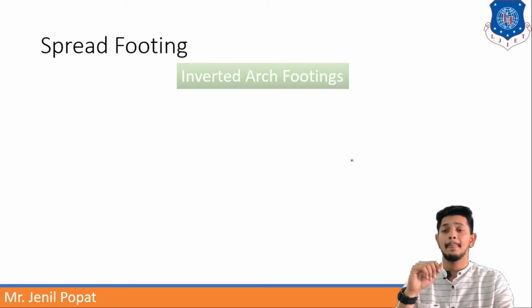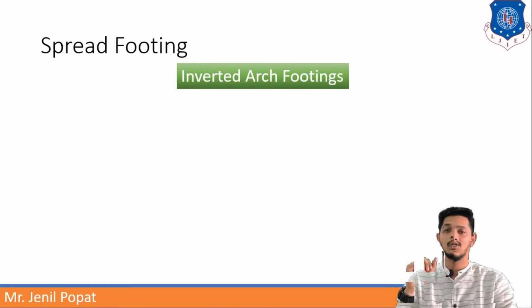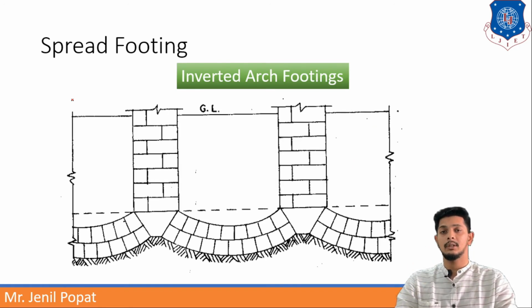Moving further, inverted arch footing. So, inverted arch footings. Here you can see a stone column and it is lying above an arch footing. Arch is made up of stone. We can use concrete also here, but inverted arch footings are mainly used for reducing depth of foundation. When it is in a soft soil and you want to reduce depth of foundation, you can use this footing.